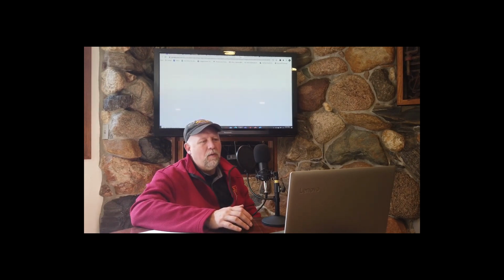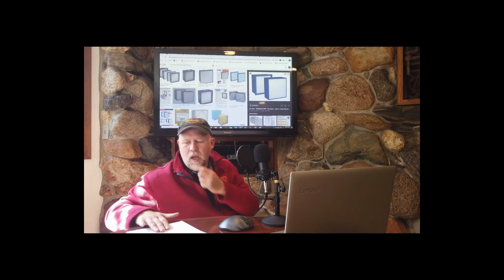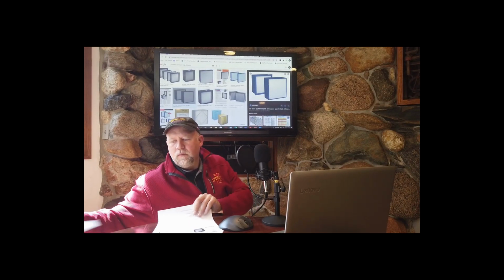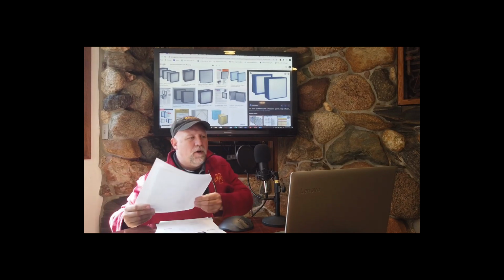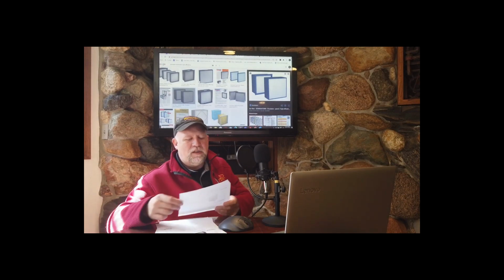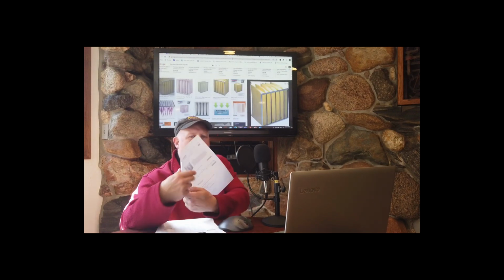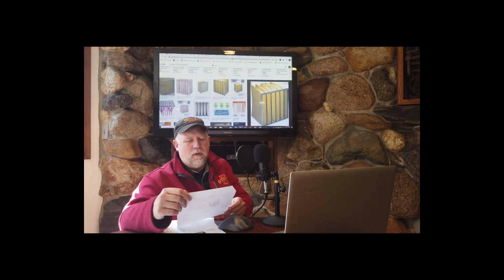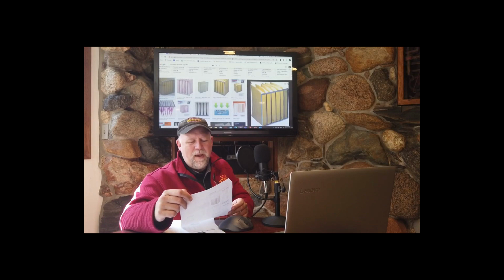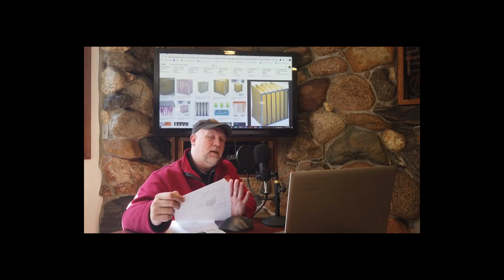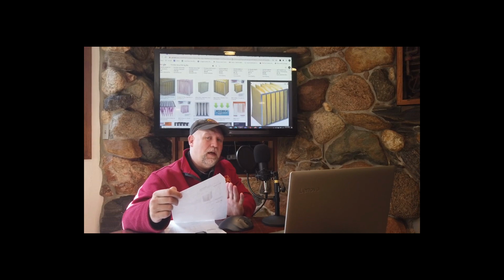All right, now let's go to the Purolator Dominator high efficiency. Oh, and I almost forgot. I'm sorry. The cut sheet on this one, that Purolator Servapack bag filter, for a MERV 11. So MERV 11, we're getting up there in efficiency.